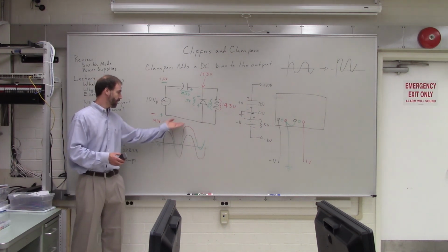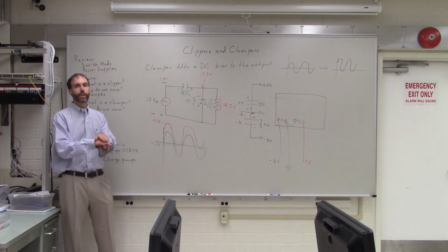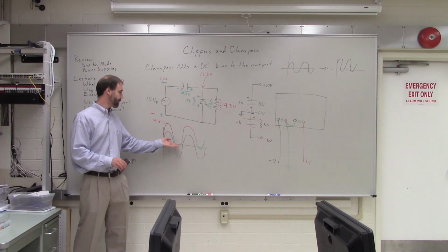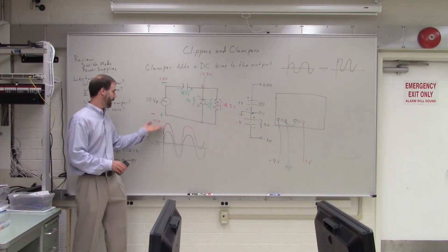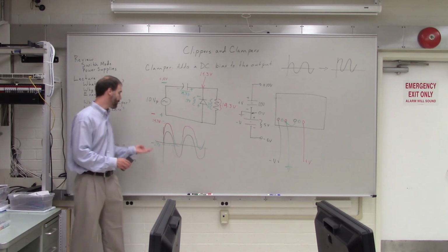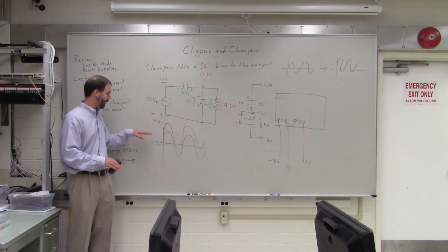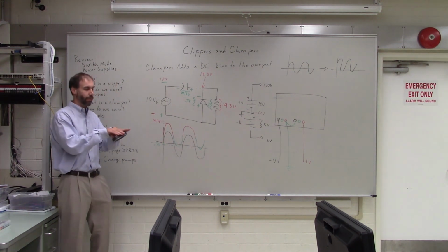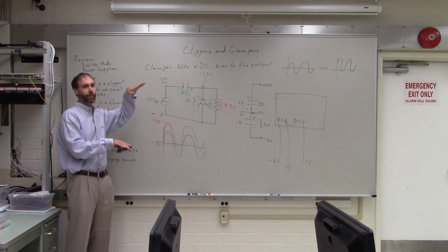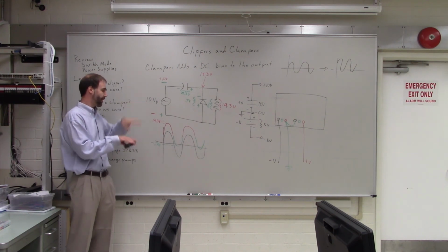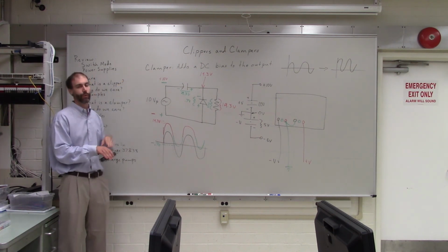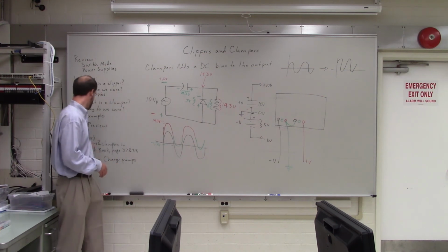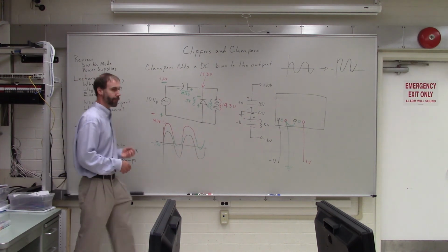So these two signals would look like they were right on top of each other. So you need to put it in DC coupling so that it shows you the signal exactly the way it is, and you can see that offset. Also, you're going to have one signal on channel 1, the other signal on channel 2. You want to line up the zero levels of channel 1 and channel 2 so that you can see how they compare to each other. See that one is at a higher voltage than the other. Okay. So that's what I wanted to say about the lab preview.